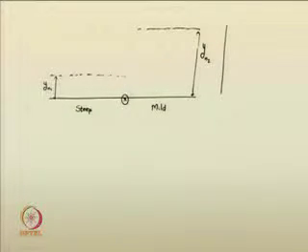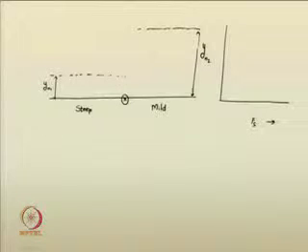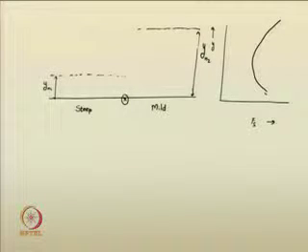Now, I am drawing the specific force versus depth curve. If I plot it, you will see that the specific force curve may be something of this form. You can note down the corresponding specific force based on the normal depth in the steep channel, because the flow is occurring from the steep channel to the mild channel.